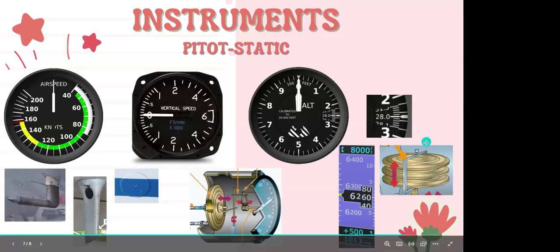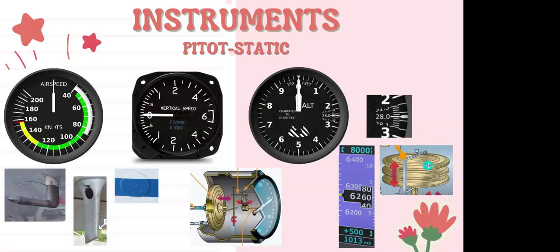And it's got that little dial on the top, you see? I don't know if you can really see, but it's at the top of that little wafer. And it dials it in. And now you've set the barometric pressure that you want to be measured against, because really, most times we're not going to be operating in a standard day.